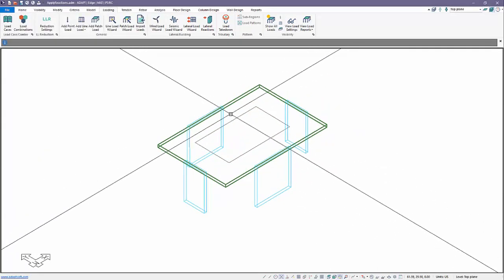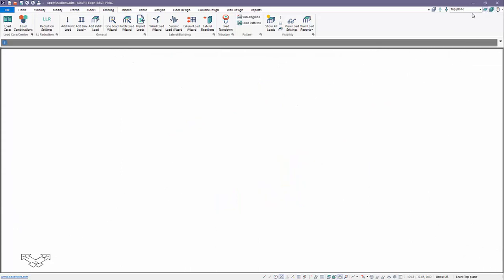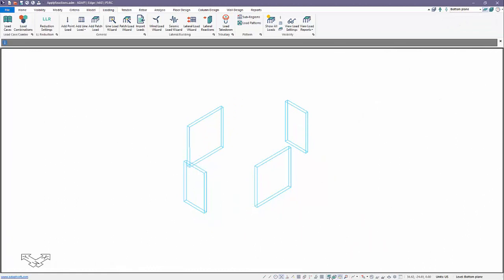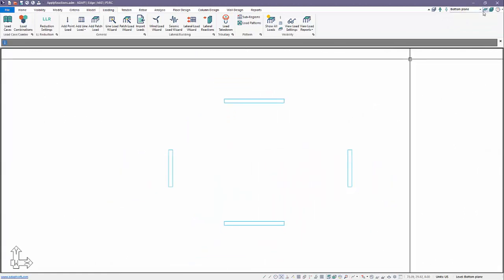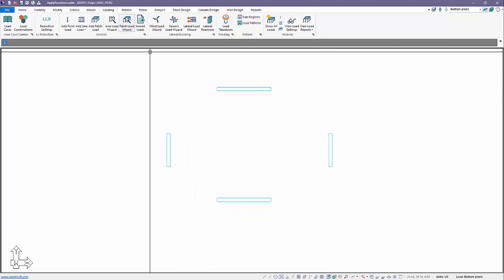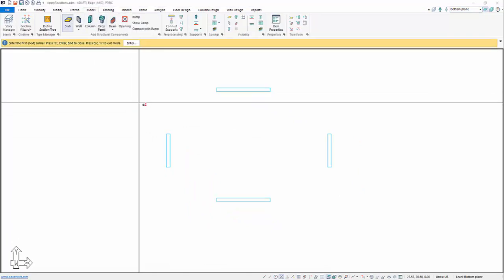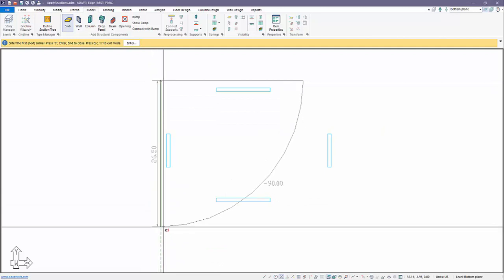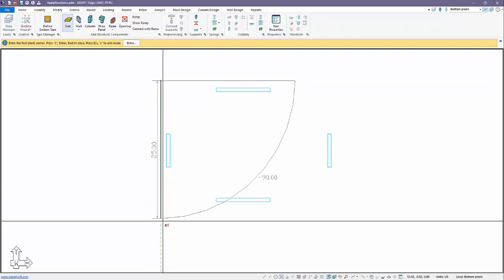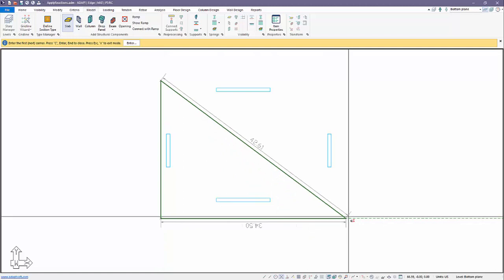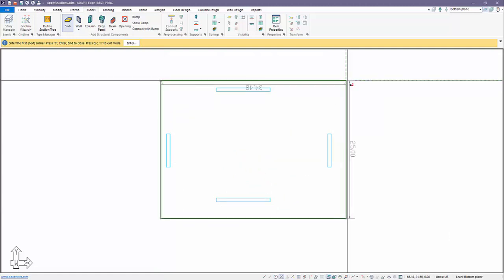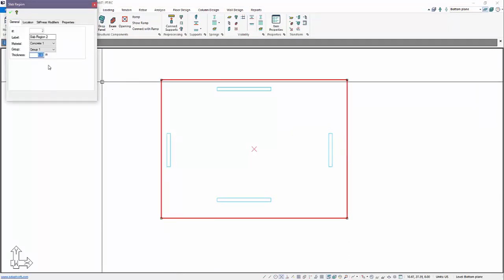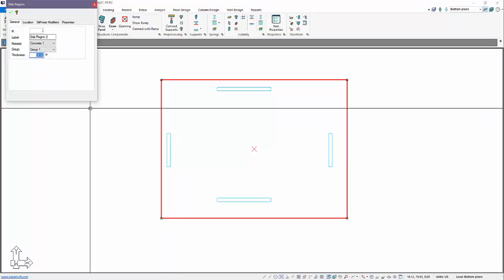We're also going to go now, and let's go back to single level mode. I'm going to navigate down to the base of the structure, and I want to model something at the base. So I'm working in single level bottom plane. We're going to go over here to model, and I'm just going to model a slab, and this will be a mat slab. It could also be footings, continuous footings, spread footings. Whatever represents your foundation could be modeled here in this level. So we'll do a mat. This mat we're going to say is 18 inches thick.